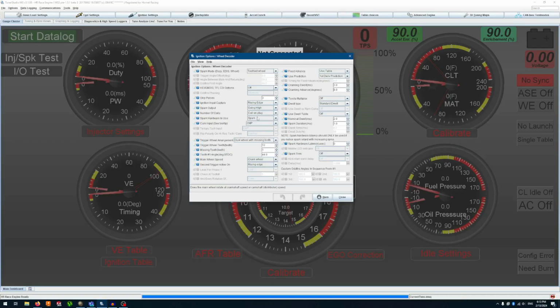A lot of this stuff I either left as it was or followed the manual to identify it. Fixed advance, I mean, we use a timing advance table. Obviously, fixed timing is for really, really old cars that maybe don't have adjustable advance. Even a distributor car has adjustable advance, using centrifugal force to spread out the little thing and change the timing as you accelerate.